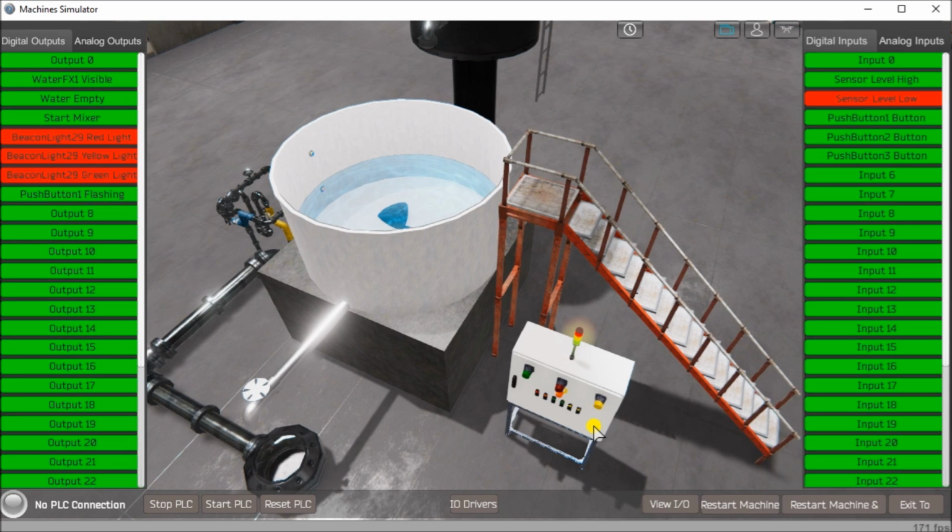It must answer questions like the following: what happens when electrical power or pneumatic air is lost? What happens when input and output devices fail? Or do we need redundancy? This step is where you're going to spend a majority of your time understanding everything about the operation, and that will save you time. It will help prevent you from continuously rewriting the PLC program logic. Knowing all these answers up front is vital in the development of your PLC program.